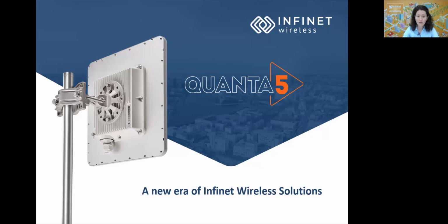Do we have Quanta 5 operating in 6 gigahertz? No, only up to 6 gigahertz. So it's 5 gigahertz spectrum, like we said in the presentation. You can see the range. One last question I see, if Quanta 5 has beamforming. No, Quanta 5 is a point-to-point product, so it does not have beamforming. It is not necessary. It is a point-to-point alignment.